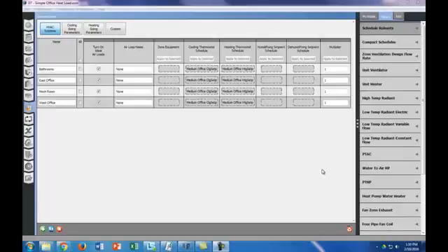We're almost ready to run our model, but we need to make a few more tweaks just to make sure that our model is following our assumptions. So the first thing we're going to do is turn off ideal air loads for the mechanical room. Ideal air loads means it's going to calculate the heating and cooling need for the spaces in an ideal model, without any HVAC system. The mechanical room isn't conditioned, so that's why we're going to turn that off.